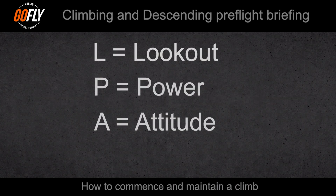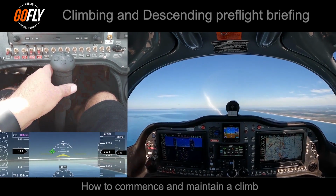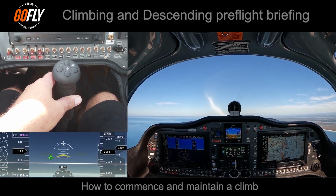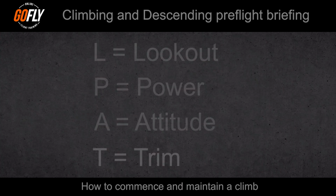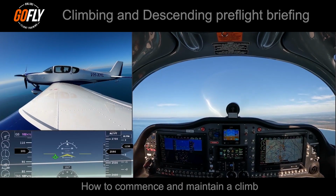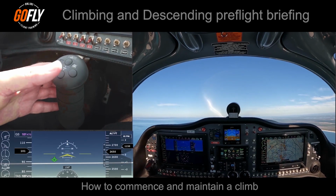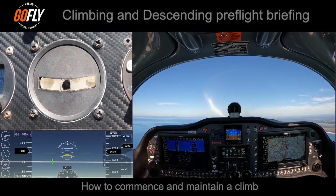A is for attitude. After increasing power, adjust the attitude for a climb attitude. T is for trim. Once the climb attitude is established and airspeed has stabilised, it is important to make sure the aircraft is trimmed correctly and the aircraft is in balance.